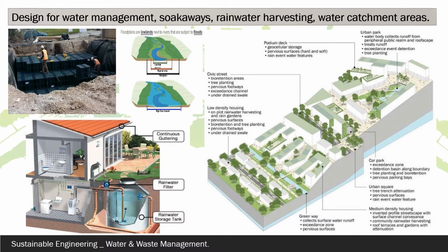But we can also look at our wider communities and how we design them in first principles to be able to capture and slow the passage of water as it moves through our villages and towns. Be that with catchment areas within our urban living areas for surface water to run off to, sit and percolate or transport away from. Can we use green roofs or green areas to slow down the passage of water and again capture it within nature? Can we create areas along our roads where trees are planted and channel the water into these areas to allow it to be removed by transpiration and also create localised cooling?